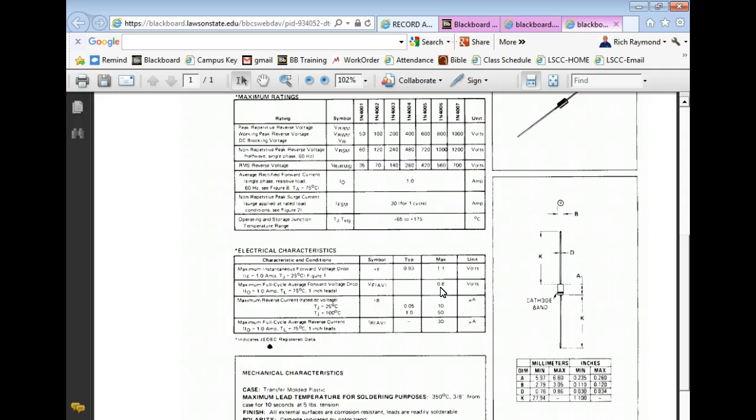But if I didn't know that, this has happened in this class, where the lab calls for a 4004, and all I got was a 4007, and we've got a 12.6 volt power supply. The 4007 has a breakover of what? 1,000 volts, and they're worried about putting it in a 12.6 volt RMS circuit. The lab book calls for this, and I don't have any of these. But see, just understanding that, right? You understand that?